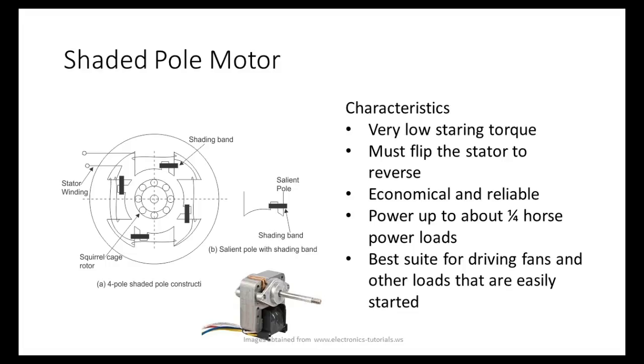Now, to reverse this one, how do you reverse it? You literally have to take the shaded pole off, the stab. You have to pull it off and turn that around and reverse that. So we don't reverse these things at all.